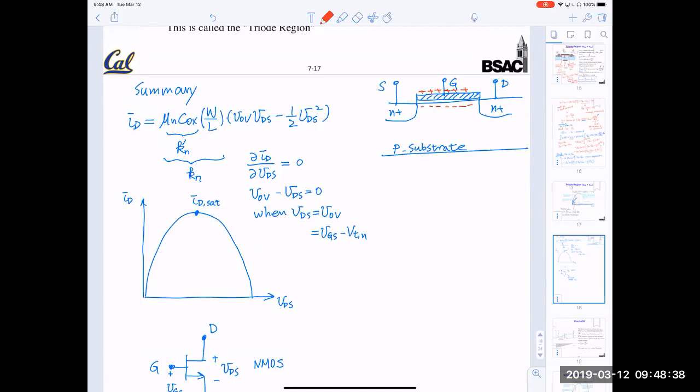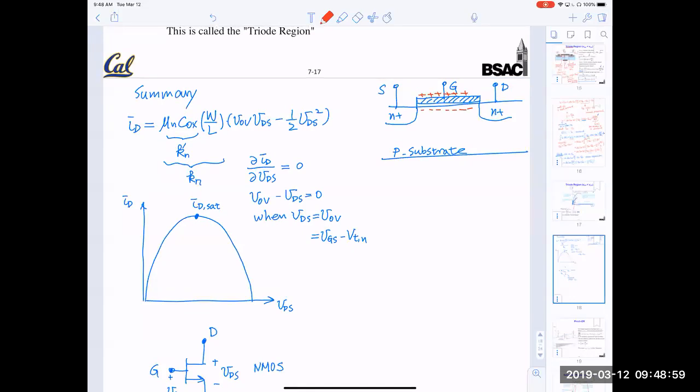And so this is called an inversion layer because it's electrons inside a p-type material, in which usually holes are abundant, but electrons are scarce. We have applied sufficient voltage to overcome the potential and induce the electrons to come out from the source terminal.